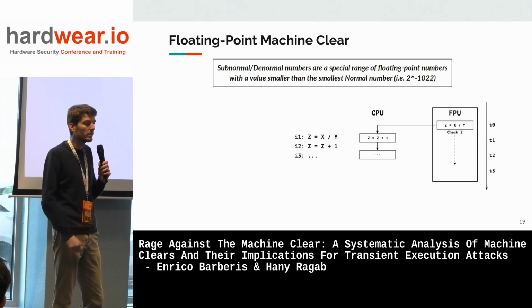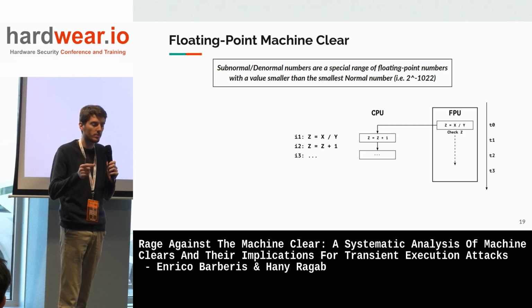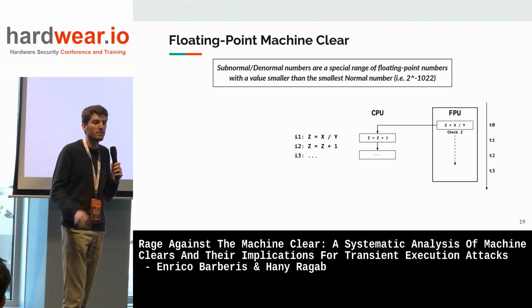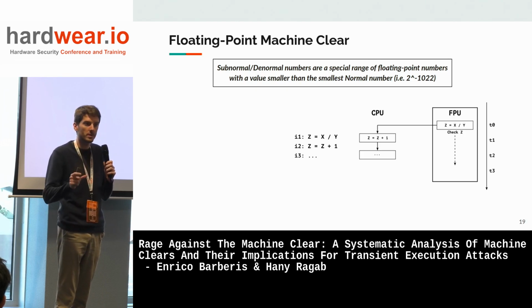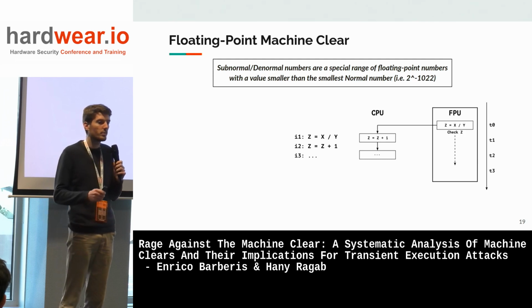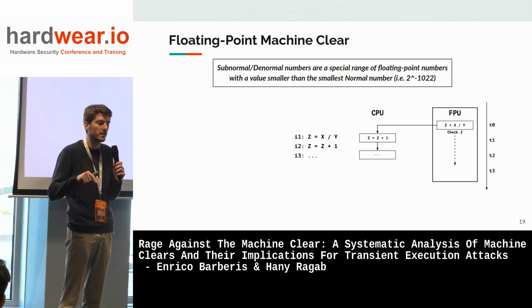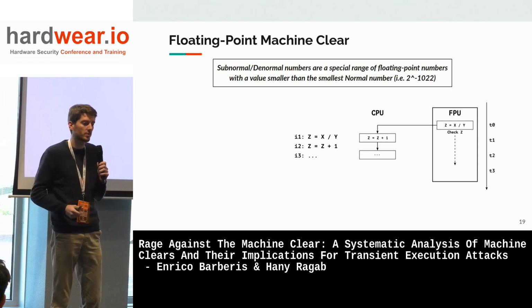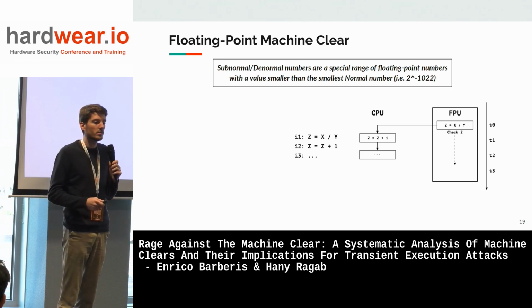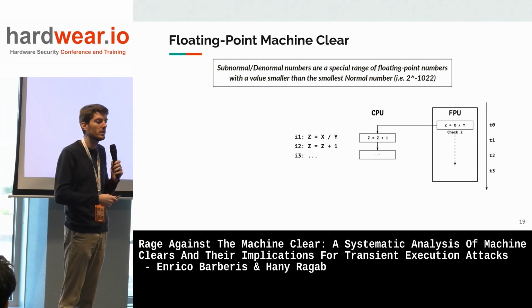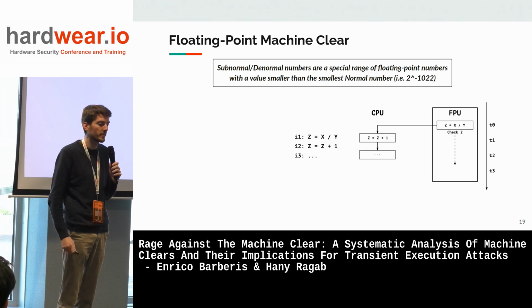Here, the issue is that the hardware, the floating point unit, is not capable of handling such a strange representation. So whenever you perform a floating point operation, the processor will blindly believe that operands and results will be in the normal floating point representation. So the FPU will blindly compute the division result and send it to the subsequent operation.